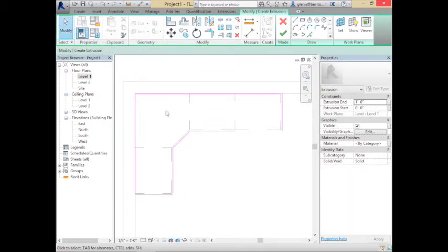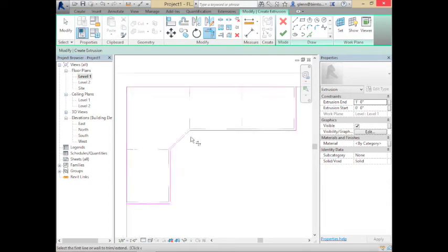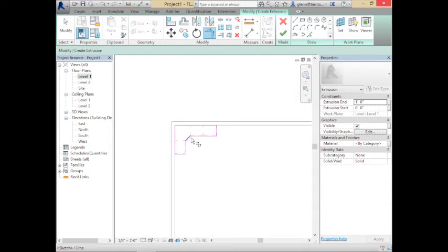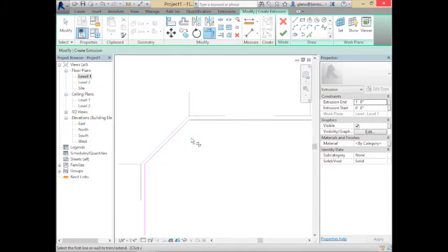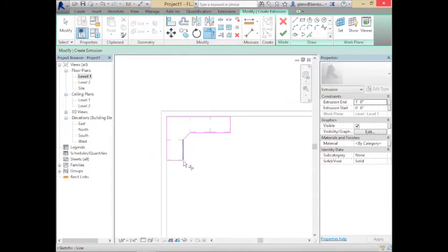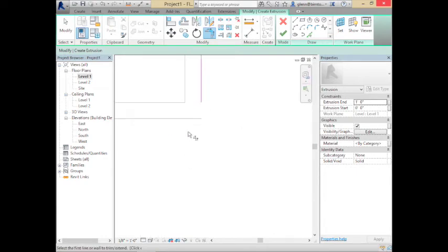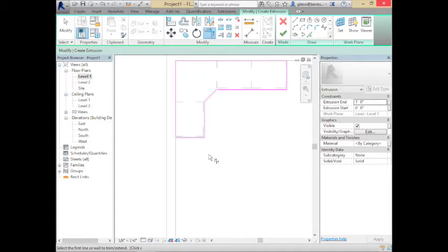We are almost good. I need to do a little trimming still. TR to trim. And I'll choose those. I can't tell if those are really together or not. They sort of look like they're not, but I bet they actually are. Hard to tell. I'll know in a minute when I try to, oops, close it. Looks like down here it's not quite together either, so maybe a little TR trim action down there. Okay, so I got my single piece of cabinetry here.